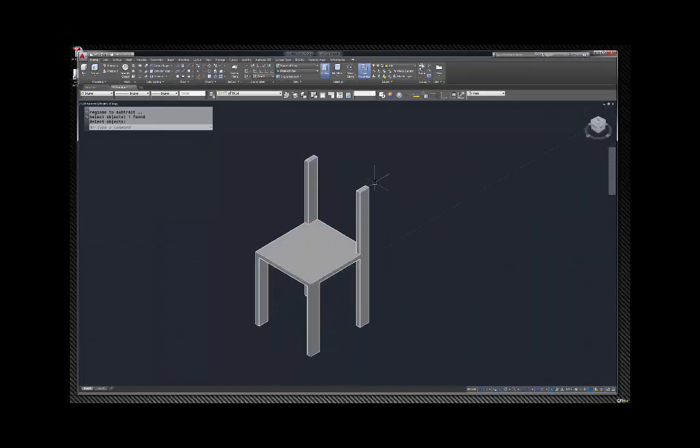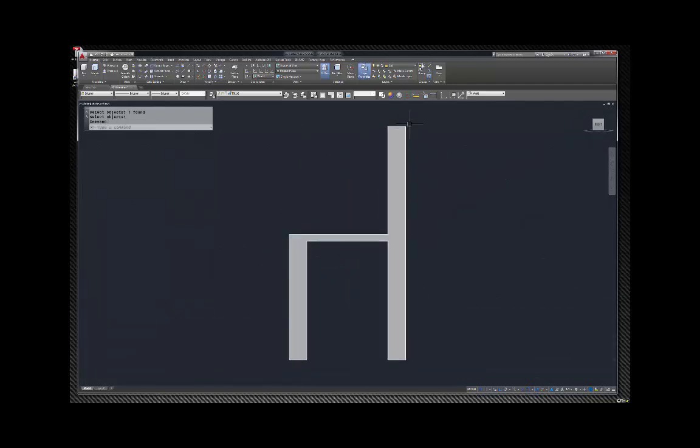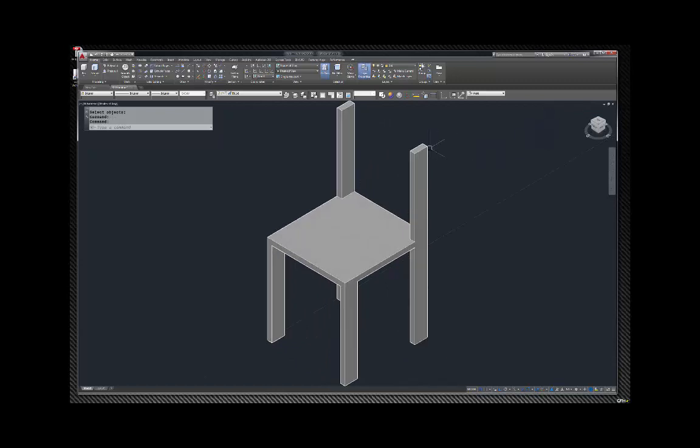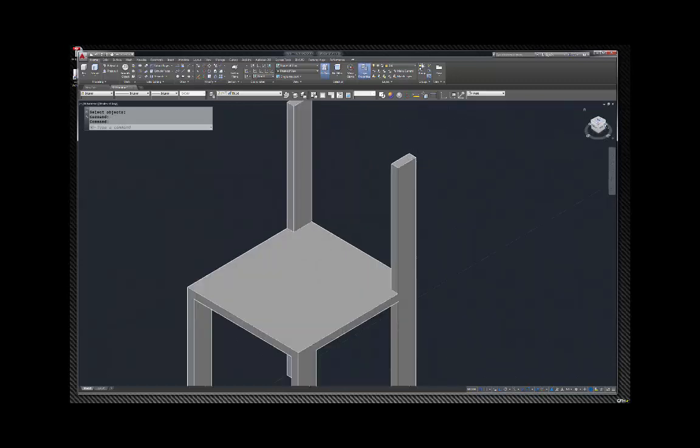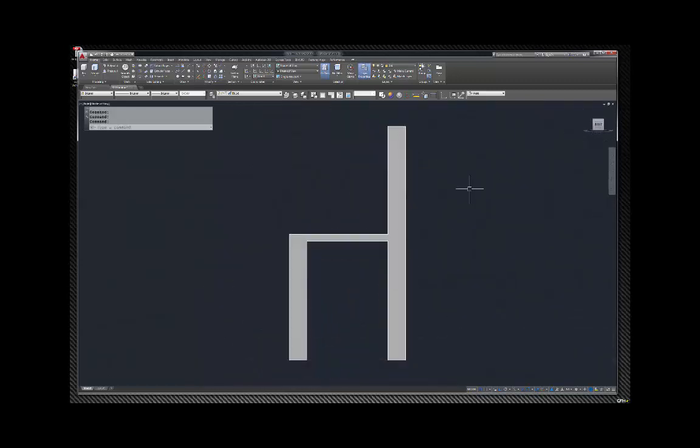And one of the things I can tell you is that chairs, the back of a chair, this portion here normally has about a 5-degree angle or rake to it. So we're going to do that, okay? And here's how I'm going to do it. I'm going to go to right, okay? I'm going to go to my Move UCS.